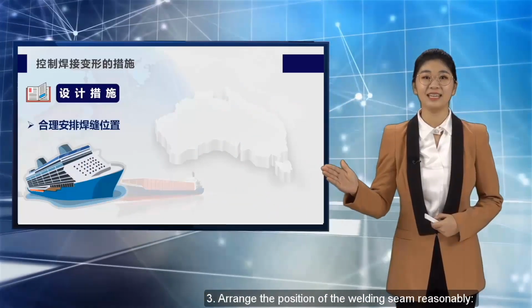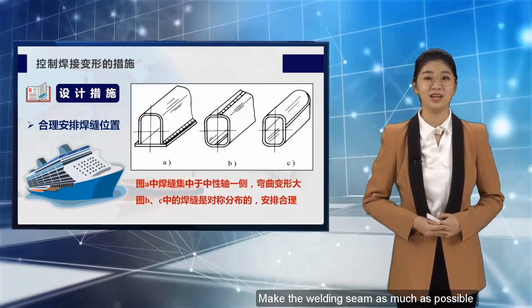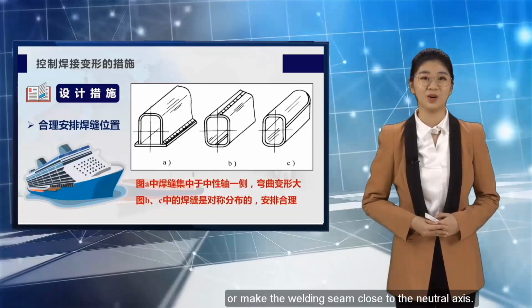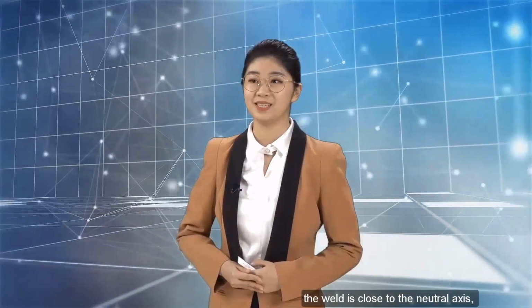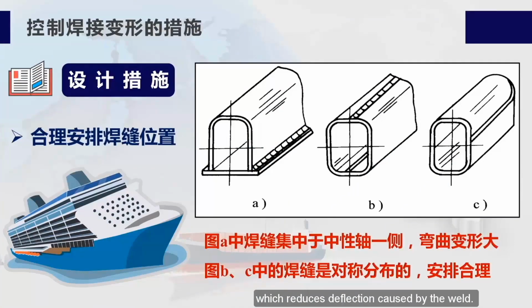3. Arrange the position of the welding seam reasonably. Make the welding seam as much as possible lie on the neutral axis of the section, or make the welding seam close to the neutral axis. The deflections cancel each other out. The weld close to the neutral axis reduces deflection caused by the weld.